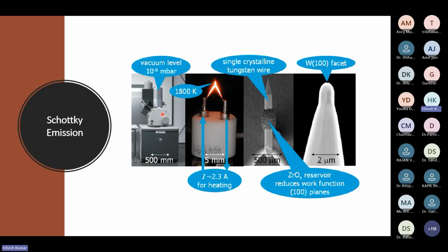These are two different chambers. First is the source chamber, where your source is located above, and here the vacuum required is 10 raised to the power minus 9. The other is the chamber where your sample is inserted, and here the vacuum is around 10 raised to the power minus 5. So these are the two different chambers for a normal FEG gun.